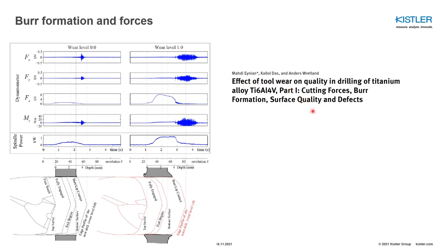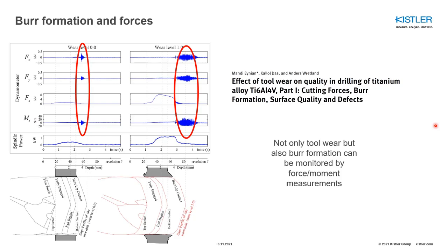As you can see here, when the wear is low, at the exit of the force level you have certain noise, certain dynamic. When the wear goes up, this level also goes up, and that is because you have this correlation between the noise level and the burr formation in the drilling operation.